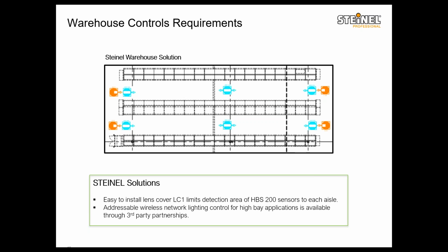There is no exception. There is no special application for that. All lights that are on occupancy control shall be turned off within 20 minutes of all occupants leaving the space.